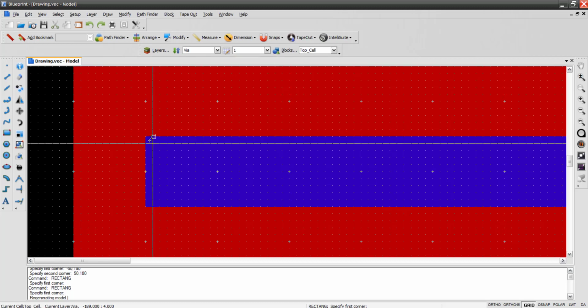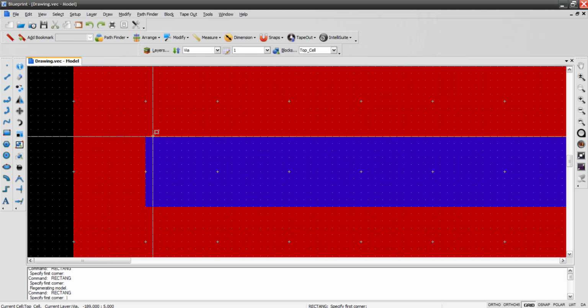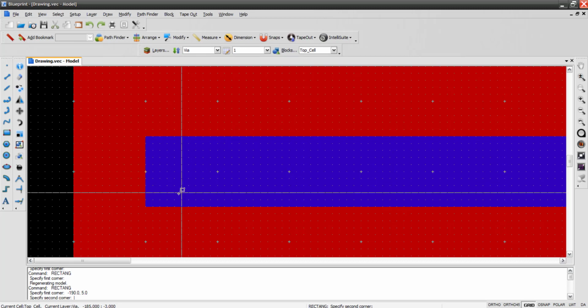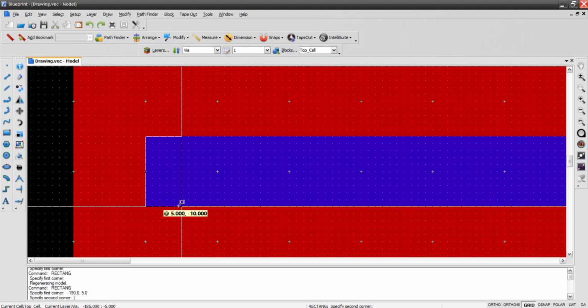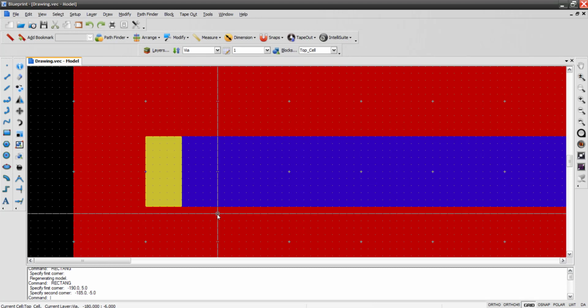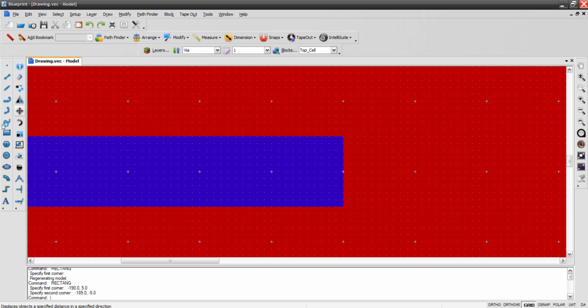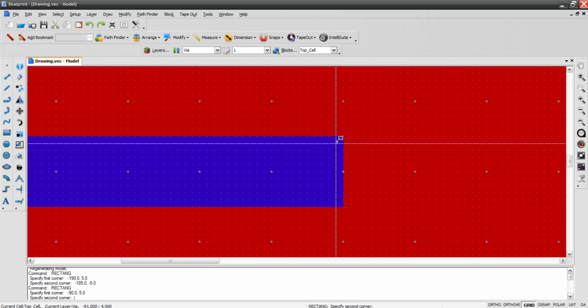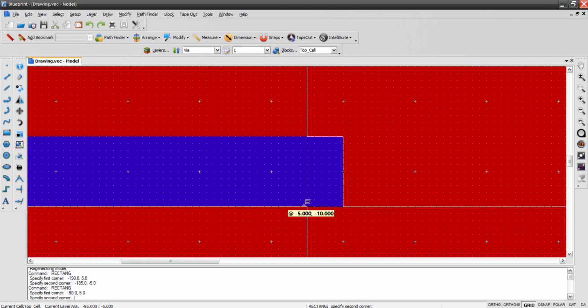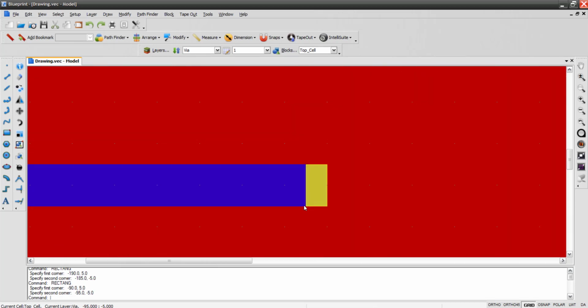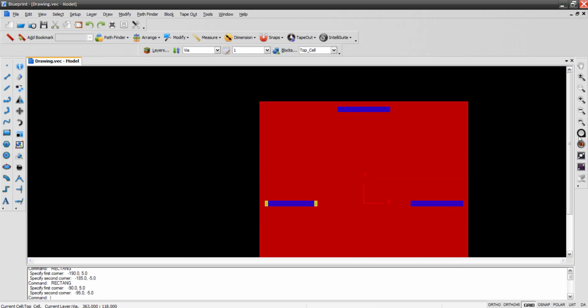It is shown here. So here I select a rectangle and using the left button of the mouse, I hold the button, I select 5 micrometers, 1, 2, 3, 4, 5 and drag it down. So it is of the dimension 5 micrometer by 10 micrometer square. Click and leave the button. And similarly, I add one more via contact in this fashion. So 2 positions I have done.